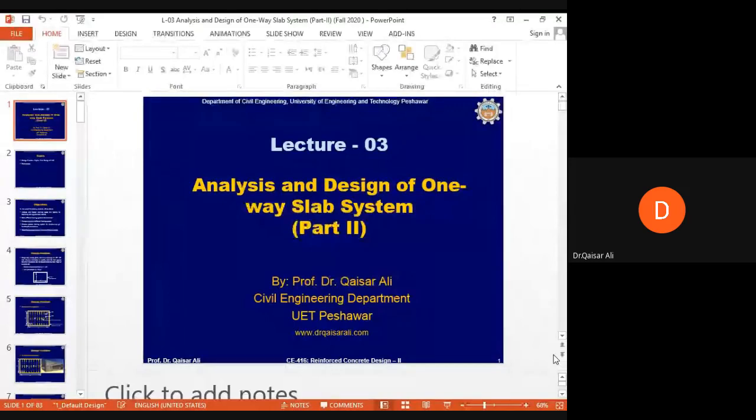No, the flexure reinforcement has nothing to do with the shear reinforcement. You have to clear this concept. If there are 4 bars in the midspan, this is very obvious, very clear, and very logical, because midspan will be subjected to maximum bending moment. So it should have 4 bars. That is correct. But why are these bars curtailed, reduced towards the support? Again, this is very logical, because positive bending moments are very small near the supports. If you draw a bending moment diagram,